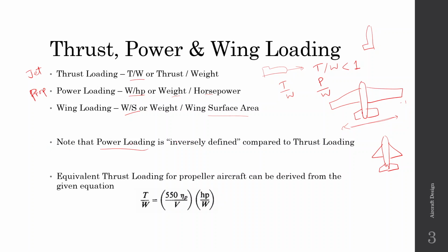Note that power loading is inversely defined compared to thrust loading. For propeller aircraft we talk about power loading, but we can also convert it back into a thrust loading for comparison, like if we want to compare a jet aircraft with a propeller driven aircraft. Then we can use such a formula to convert this power loading into thrust loading.